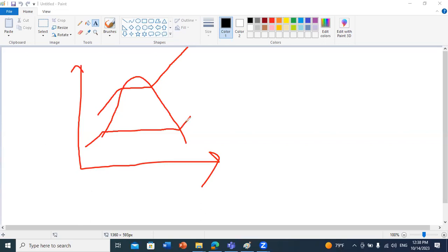So this is point 1, isentropic process until point 2. They told us that we left our condenser at saturated liquid, point 3, and we calculated H3. Now, since in the throttling valve H3 equals H4, this will allow us to determine the condition at the exit of the throttling process.